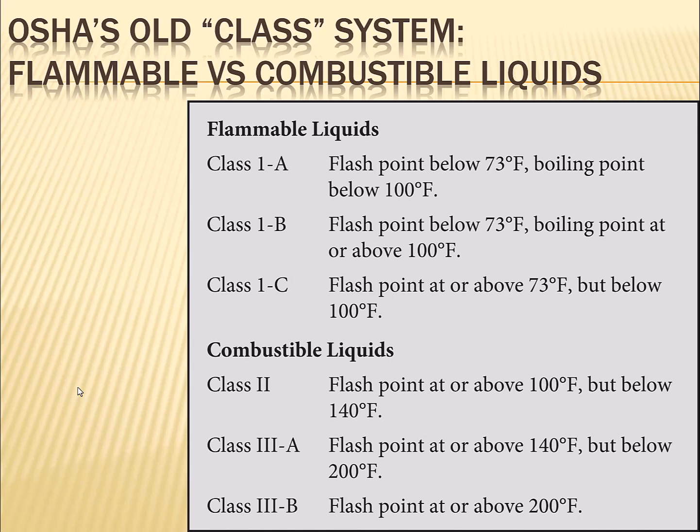Now, in modern times, we've replaced this system with a category system instead of classes. It's part of this Globally Harmonized System where we're trying to make a standardized system across the world. And in doing so, category 1 is still the most dangerous, but they've gotten rid of the word combustible. So liquids are no longer considered combustible. They're either flammable or they're not. What we still reserve the word combustible for in the safety business is dust. Anything powdery, dusty, ground metals, all kinds of things like that.